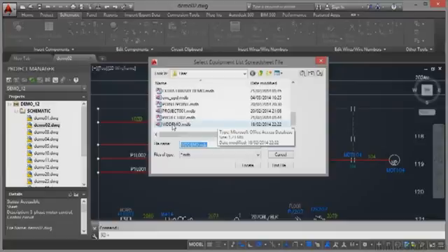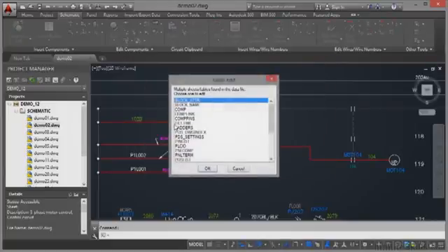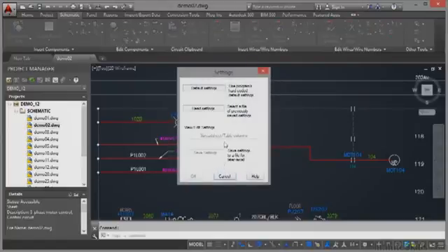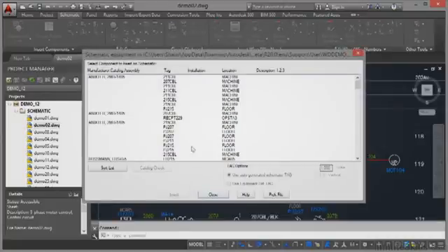So when you install AutoCAD Electrical, you get this MDB file because there is a WD Demo project set up by default. So if I double click there, I'm going to look for components because I need to insert a component into my drawing. So I go Component and I click on OK. I'm just going to go for the default hard-coded settings for AutoCAD Electrical, and then I'm going to click on OK like so. Now there's all the default component settings. So you can see, look, there's all different manufacturers there that come in as defaults in AutoCAD Electrical.